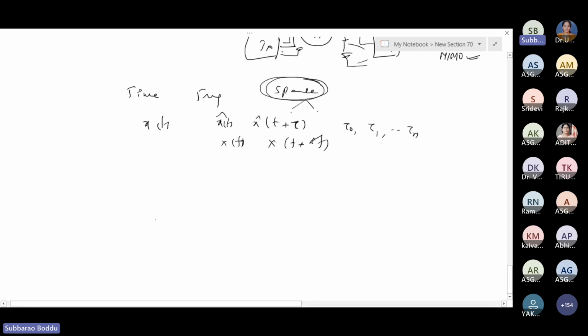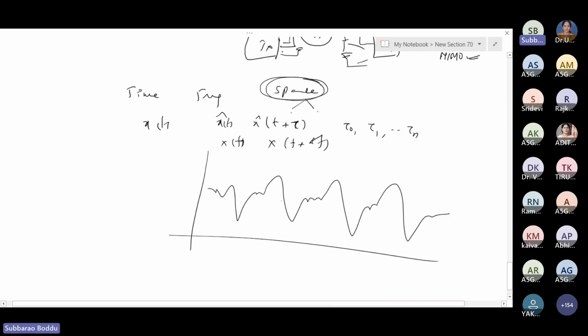Let us suppose we have flat and slow fading channels. If you see how the signal varies, my signal is varying. If you take the mod square of my received signal y of t, this usually follows a distribution like the exponential distribution. This is basically the envelope squared, so we analyze it like this.